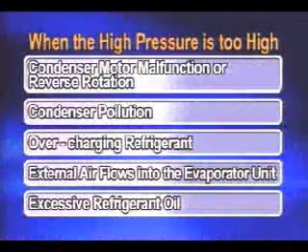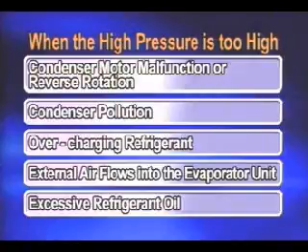When high pressure is too high, check the following: condenser motor malfunction or reverse rotation, condenser pollution, overcharging refrigerant, external air flows into the evaporator unit, excessive refrigerant oil.